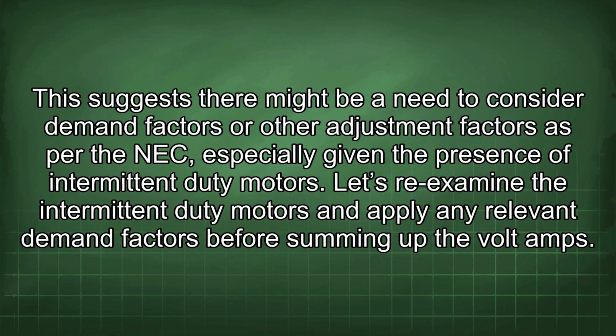This suggests there might be a need to consider demand factors or other adjustment factors as per the NEC, especially given the presence of intermittent duty motors. Let's re-examine the intermittent duty motors and apply any relevant demand factors before summing up the volt amps.